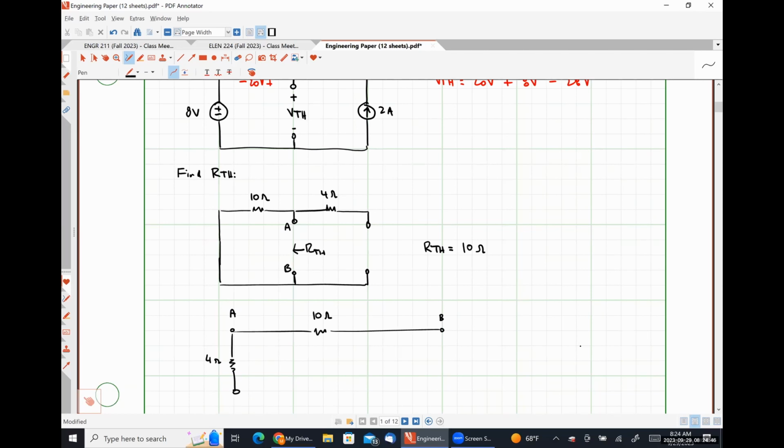When we're finding the Thevenin equivalent circuit with respect to the 6 ohm resistor, we're effectively making sure that the 6 ohm resistor absorbs the exact same amount of power, and we don't really care about anything else, right? We're ensuring that the voltage drop across that resistor stays the same, the current flowing through that resistor stays the same, and therefore the power absorbed by that resistor stays the same. So doing it with respect to the 4 ohm resistor or the 10 ohm resistor, we're definitely going to get a different Thevenin voltage and a different Thevenin resistance. So it's hard to say that the Thevenin equivalents with respect to different resistors are going to be equivalent to each other.